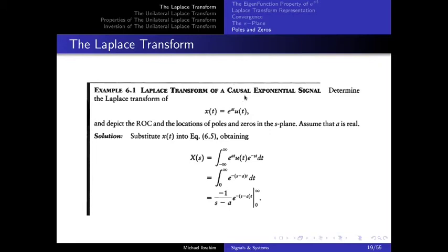If you remember, a causal system is a system whose impulse response is 0 before time t equals 0. So the description of causality is only for systems. Signals cannot be causal. So how is that in the textbook he's calling this signal causal?